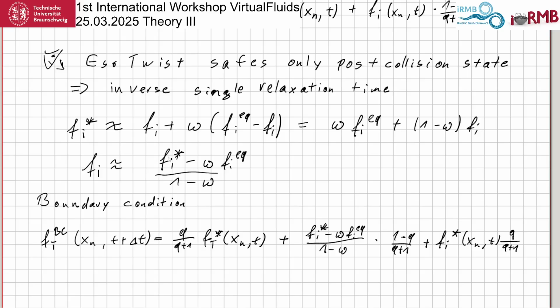But why do you want to know the skin friction in the first place? This may sound like a stupid question of myself, but there is one point that you have to distinguish. If you come from the Navier-Stokes world and you want to have forces on the boundary, then you have to integrate over the stress, for example.